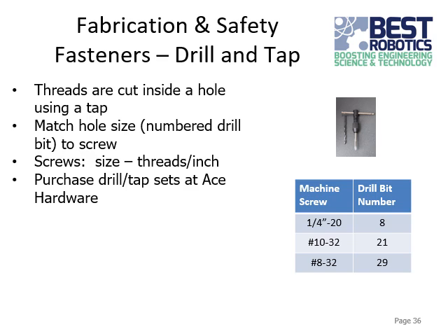What tapping a hole means is basically you're taking a hole and using this tap to actually cut threads into the hole, so that when you're done, you can screw a screw into it. You don't necessarily need a nut on the other side, because the screw will fit perfectly where it has to screw in. A lot of times these come in sets with taps and the corresponding drills that go with them, so the drills are the right size for the tap, and you can get those at a hardware store.